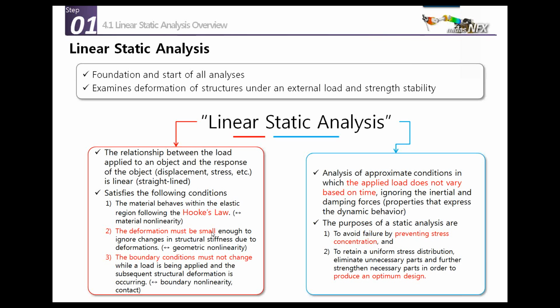The deformation must be small, so this is a requirement, and you should always check that your deformation is small. And the boundary condition must not change. So when the load is applied to the structure, it stays at the same position, and the orientation of the load also stays the same during the analysis.